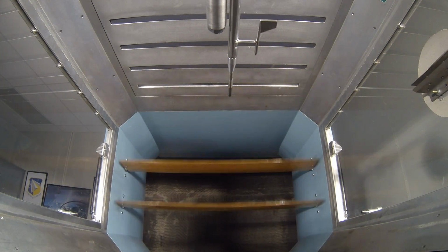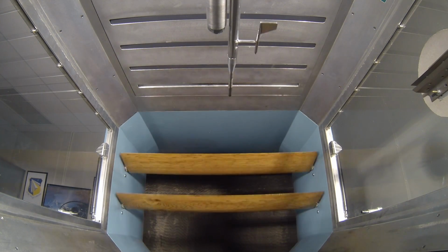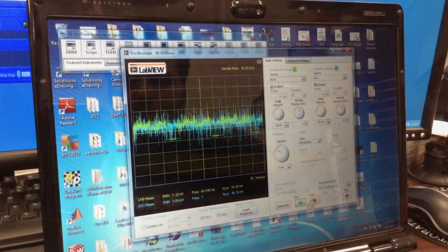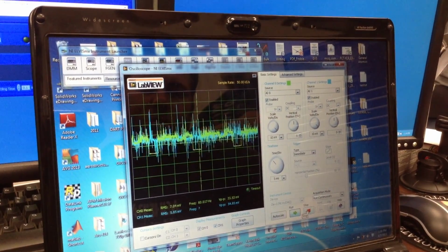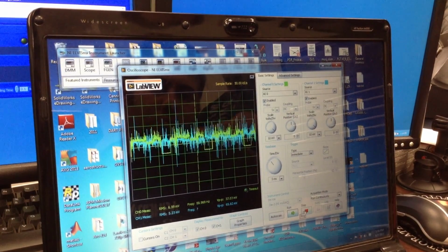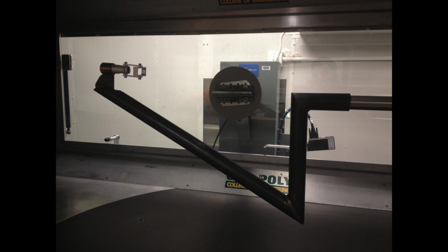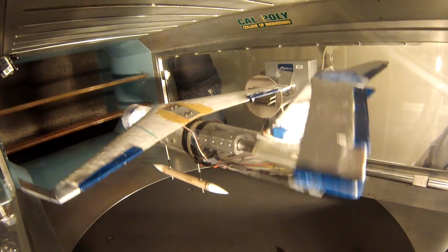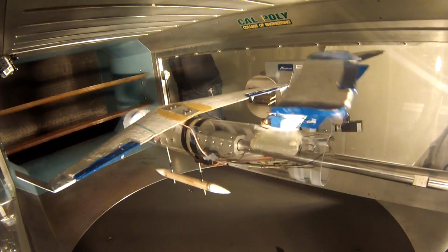The addition of a vector duty motor will enable the Gust generation system to generate gusts at up to 14 Hz. The Gust generation system also carries a full sensor suite, which is used to measure the performance of the system as well as characterize the gusts being generated. This Gust generation system, when combined with the university's 5 degree of freedom sting mount, allows for wind tunnel models to be flown within the wind tunnel and the gust response of each model to be studied in detail.